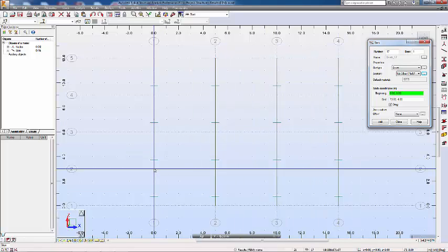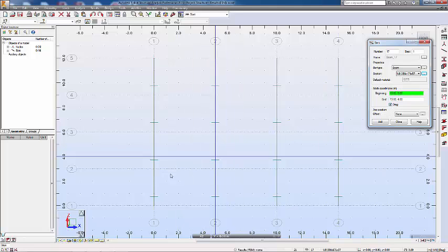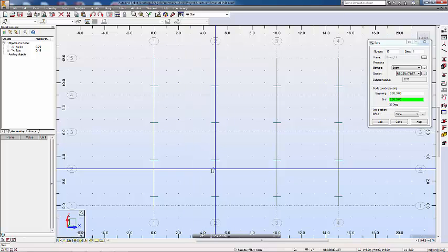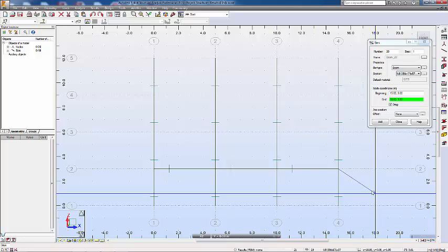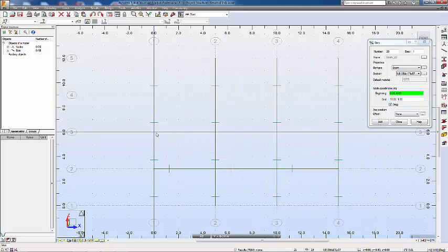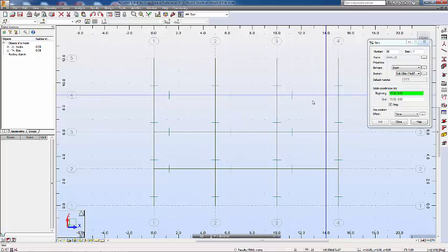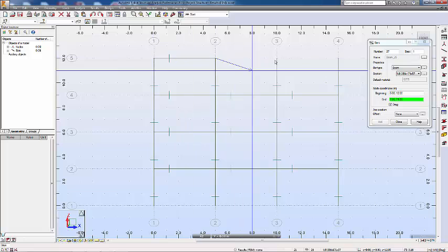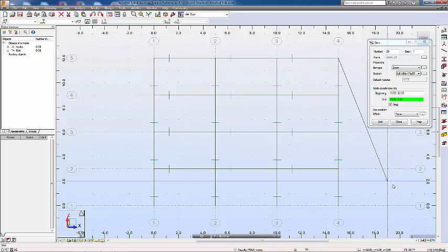So we start to draw the beams, and then notice that the drag is on, so we can draw this one continuously for every story. So once finished one story, press the ESC key to exit the current line, and then draw the next one, and then exit, and then draw the next one, ESC, and then drag the next one. So that's it. So that structure is finished.